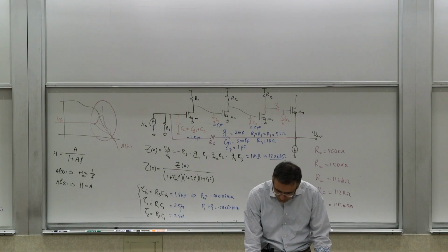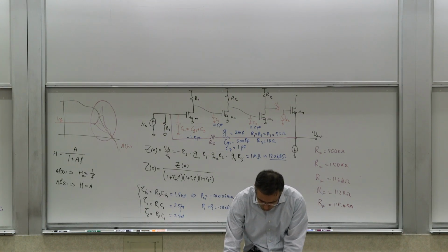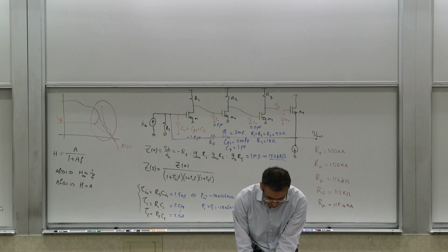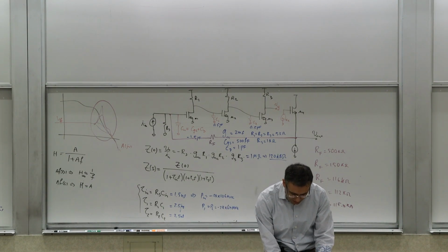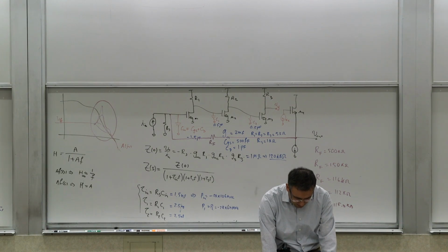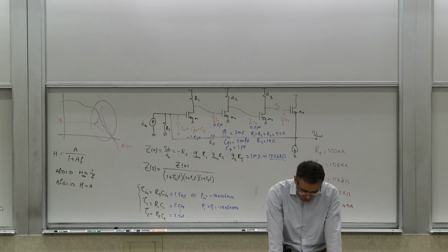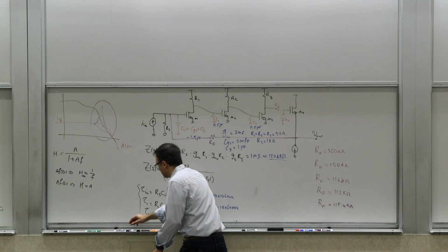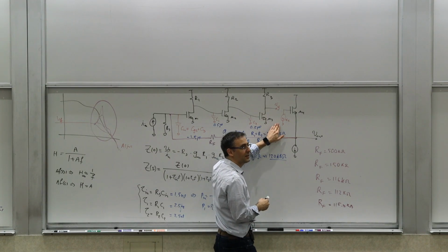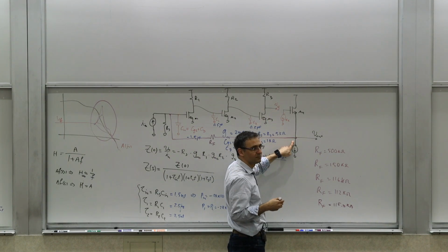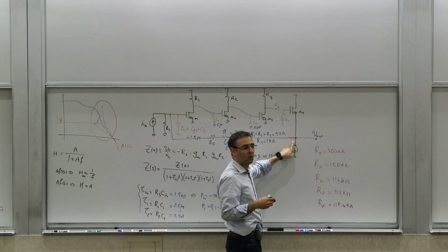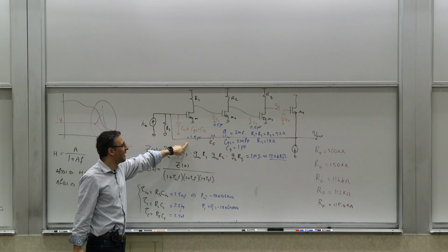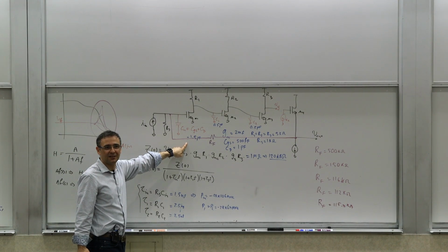But now, let's look at something. If you continue looking at this, what you will see is that we can actually calculate this loop gain, right? We can evaluate what this loop gain looks like if we break it here. So the gain from here to there is what? Well, is it still 1? Because now you have this RS and RF, right?